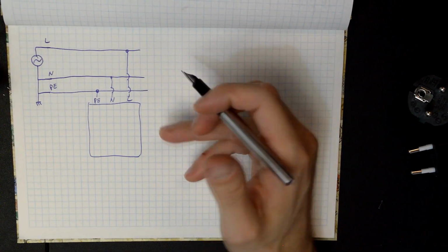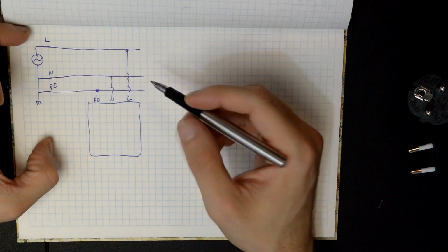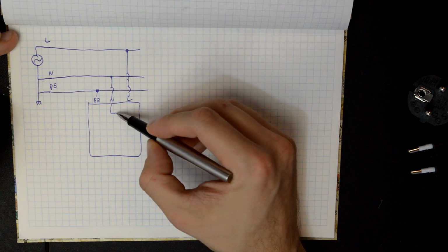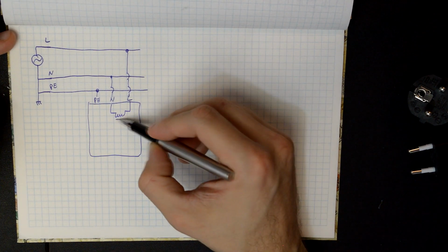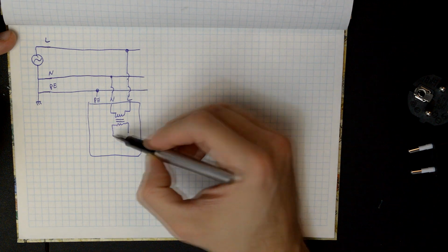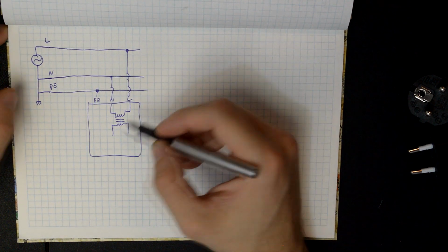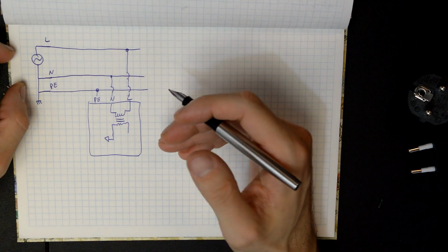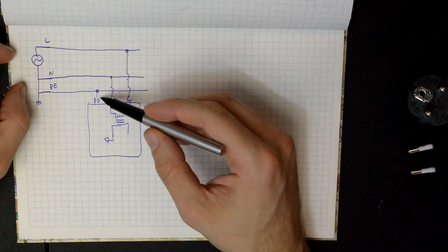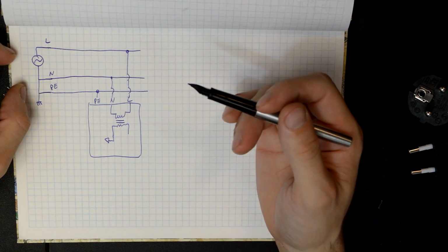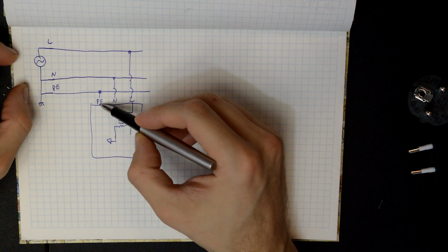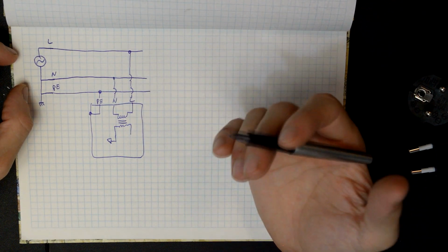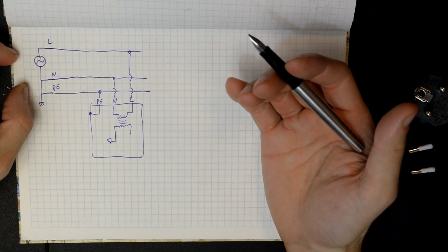So the 3 wires go into your unit, and the actual power comes through the 2 wires, so the live and the neutral. Then inside you probably have an isolation transformer, and from this you're powering your device. You rectify it and so on. And this is where you get your local ground inside your unit. Now the protected earth is there mostly as a safety measure. So this might be connected to the housing if the housing is made from metal, like is the case in washing machines or the power supply.